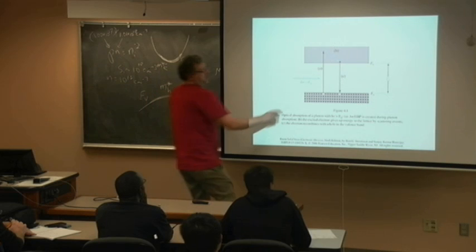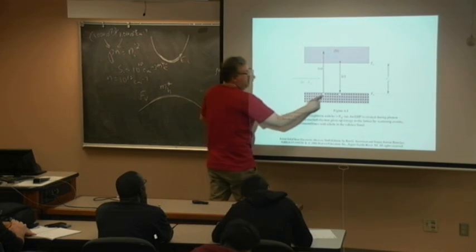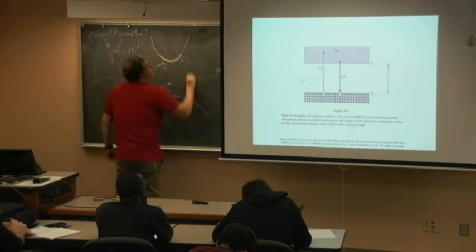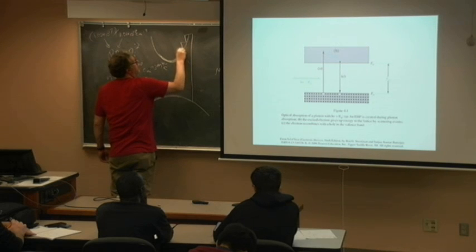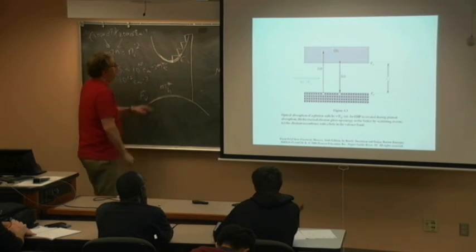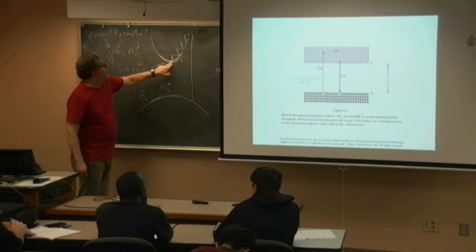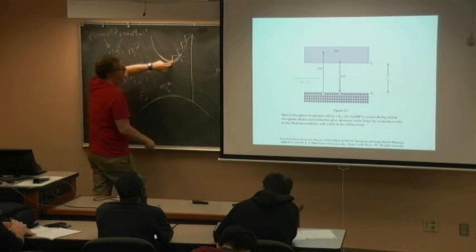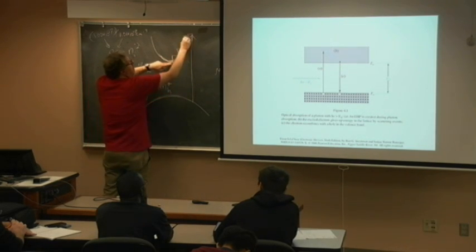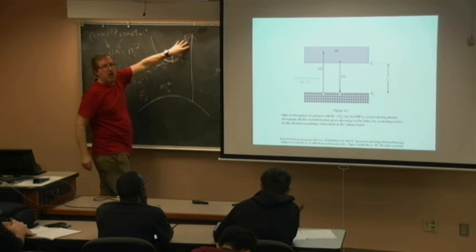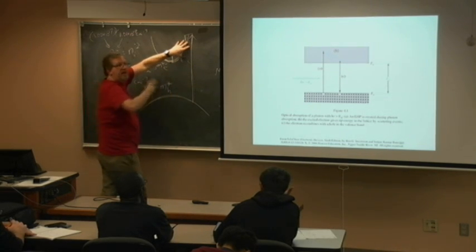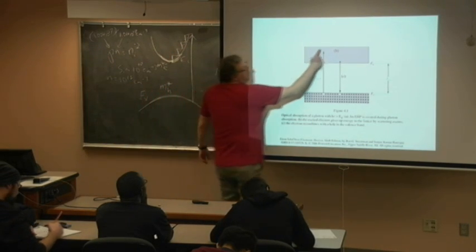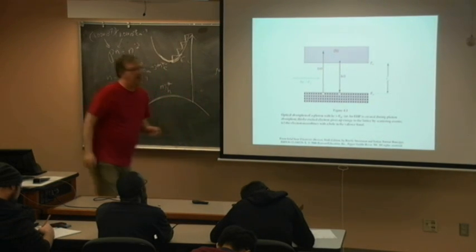Do you remember what this is? This is where a high energy photon is greater than band gap, so it goes way up here, and then it's going to move down to the global minimum, right? So this is the global minimum. So it may capture a photon that is larger than the band gap, and then there's this. What do you call this? So thermalization, it's casting off heat, it's casting off phonons. It does this thermalization where it ricochets down and loses its heat.